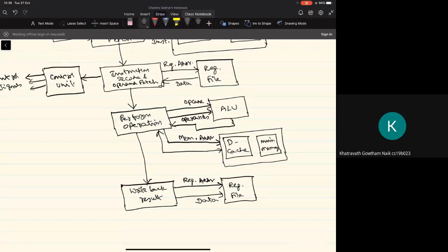Typically they are implemented using the sum and reduction methods, followed by carry lookahead based addition, and we have seen that the amount of time it takes, even for 32-bit multiplication, is not the same as the time it takes for 32-bit integer addition. So the time taken for the addition operation is different from the time taken for the multiplication operation, even for the same size integer operands.